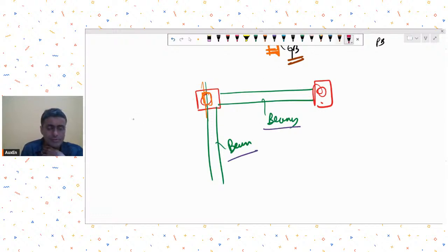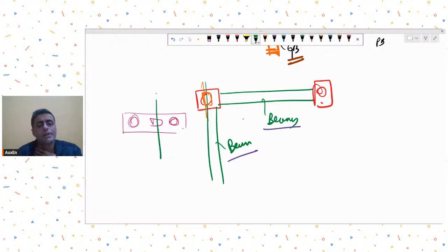If not, then you should provide multi-pile pile caps, which will be able to resist moment about the axis of the piles. I mean, about that axis where the piles are given spacing, they will be able to resist moments. So this arrangement shall be provided. If not, ensure that pile caps are tied properly to each other with beams.